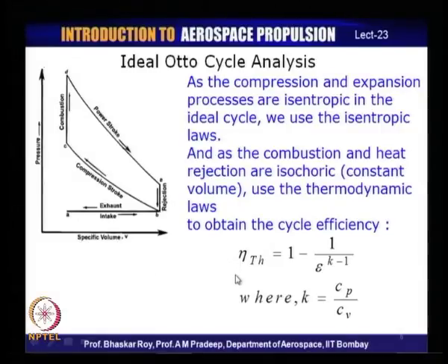So, you see it is quite simple that if you prima facie have the compression ratio available with you, you know the working medium that you are using, you can quickly find out what the cycle efficiency is likely to be. And as we shall see, this allows the cycle designer, the engine designer, to indeed configure a cycle or configure an engine even before it is actually built.